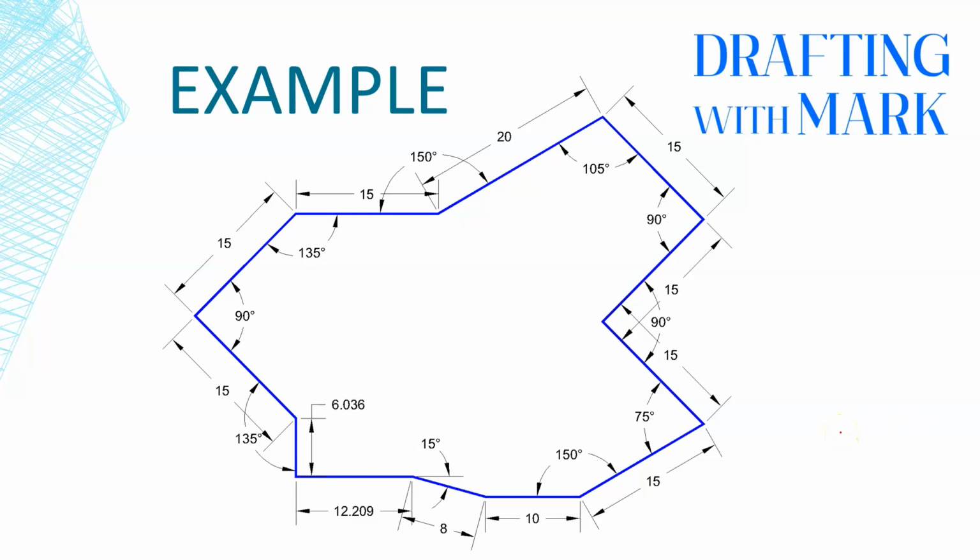All right, so on this one, what I'm going to do is try to figure out where I'm going to start from. I've got a lot of things going on in this drawing, but there is one distinct place that you have to start from, and it's going to be located at this area. The reason I'm starting there is because the two dimensions next to that starting point are not whole numbers. These two numbers are decimals and things of that nature at the end of it. So we're going to let AutoCAD fill that out for us.